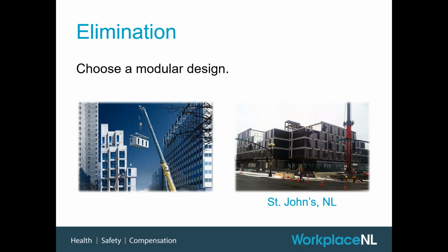And then once the individual sections are done, and a lot of them are completely done, I mean, interiors and the works are completed, all the individual sections get stacked on top of each other, again using a crane to reduce the need for workers to work at height. Now, don't get me wrong, there's still some work at height with the modular systems. Obviously, you've got to make sure that these individual modules are tied together. But this is, again, a reasonable way to reduce the amount of actual work that you've got going on at height.